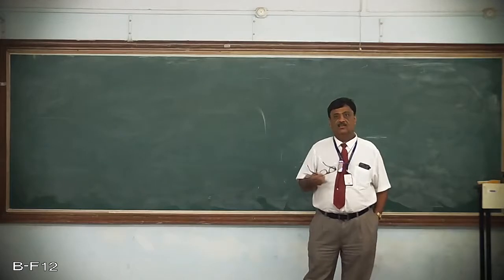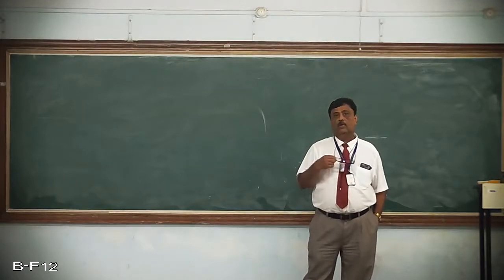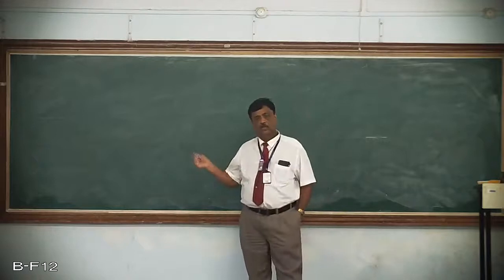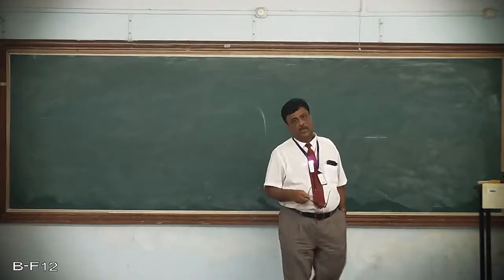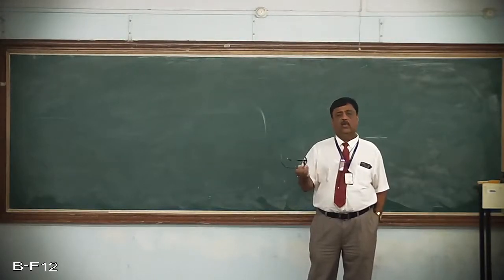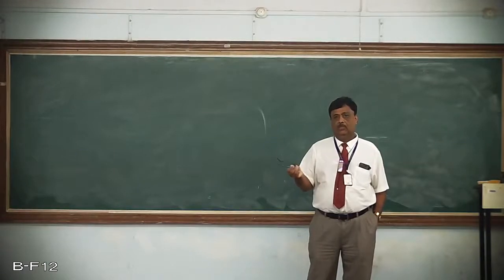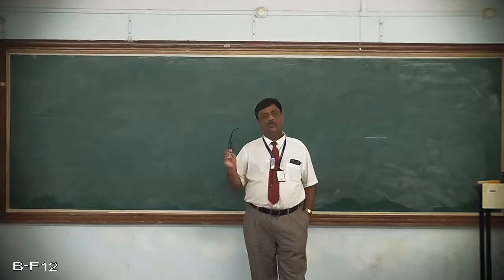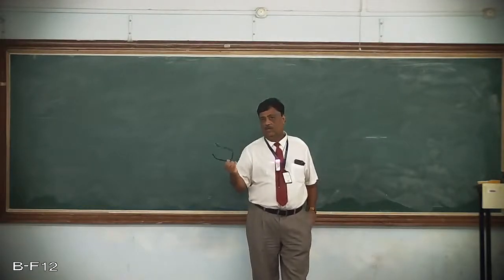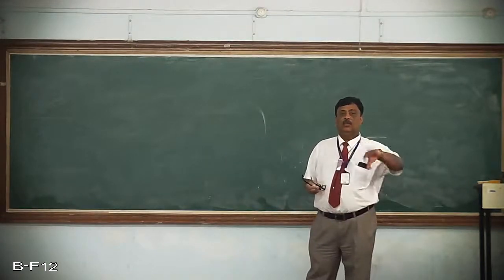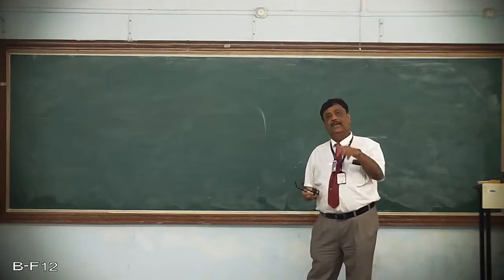Then is there any chance that we can go for special elements which will take care of even curved boundaries? If you look at the shape functions associated with the 3-noded element, they are simply zeta, eta, and 1 minus zeta minus eta. That is, you have only 3 choices: 1, zeta, and eta. Even for the 4-noded quadrilateral, we find only 1, zeta and eta terms. There are no higher order terms like zeta square eta, zeta eta square, or zeta square eta square.